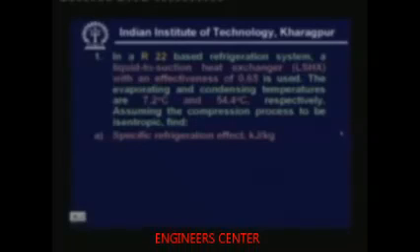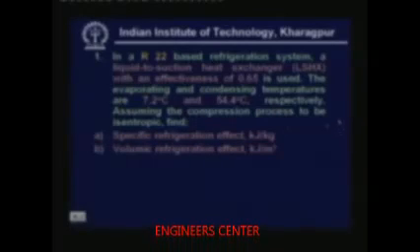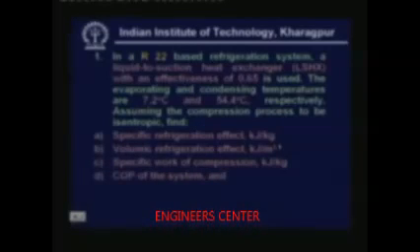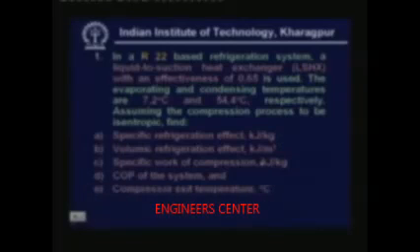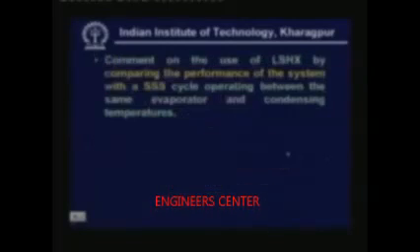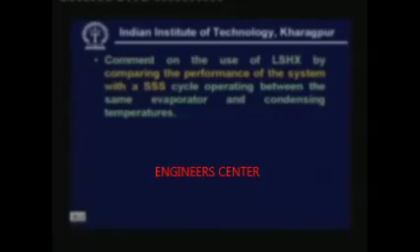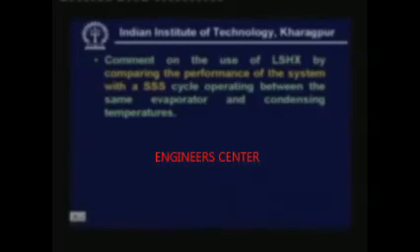specific refrigeration effect, volumic refrigeration effect, specific work of compression, COP of the system, and finally compressor exit temperature. And comment on the use of liquid suction heat exchanger by comparing the performance of the system with a SSF cycle operating between the same evaporator and condensing temperatures. That means basically it is a single stage system. We have to make performance comparison between a system with liquid suction heat exchanger and a system without liquid suction heat exchanger. Both of them are operating between the same evaporator and condensing temperatures.